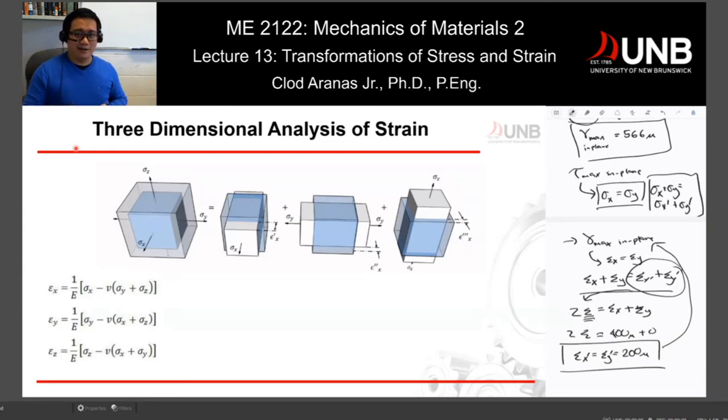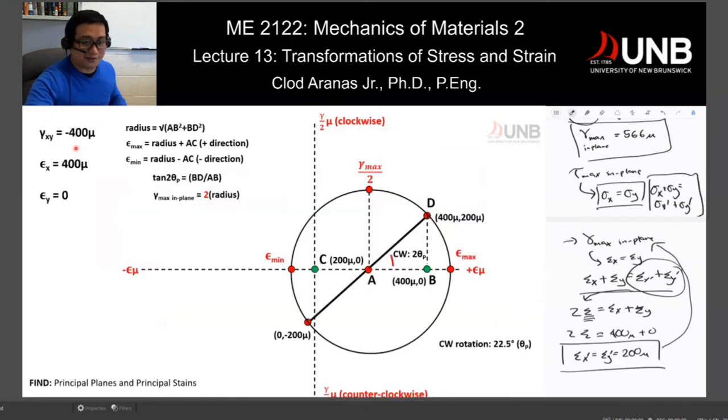You are zero in z. But if you pull something or compress something, it will deform in three-dimensional ways. So your strain is not really plane strain. That's what we are doing at this point, assuming plane strain condition. But remember that our assumption is we put the constraint, we are deforming it, but that's not the practical approach.